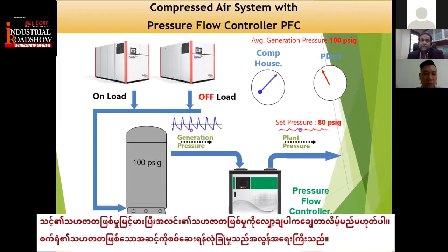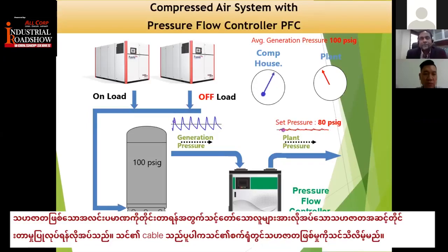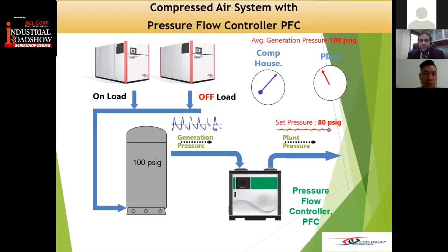So care must also be taken with the harmonics level. If you have a high harmonics level and reduce it, you are not going to get any saving. But in terms of safety, it's very important to check the harmonics level of your plant, right? To measure the harmonics level, of course, you need to get the right people to do the measurement. If your neutral cable, your main incoming cable, is hot when you touch it, it's like very hot, you roughly know these are the symptoms of harmonics present in your plant. So you have to quickly do a harmonics level measurement.